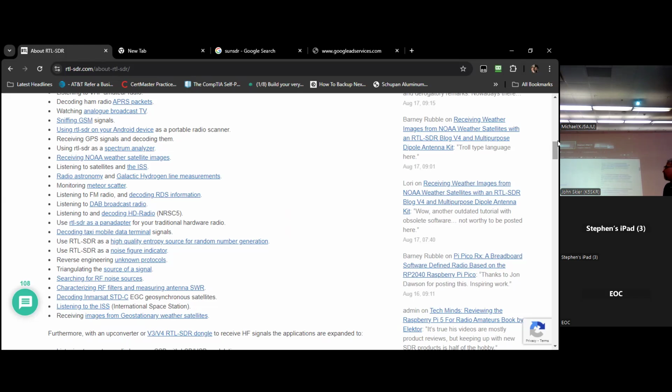A lot of these software packages meant for satellites have the ability built into them to use a rotator. So if you have a rotator on your mast, they can rotate the tower for you from the software to keep the track on the satellite. And some of them will not only do azimuth, but they'll also do elevation. If you have a dual rotator that will do azimuth and elevation, you can control both.